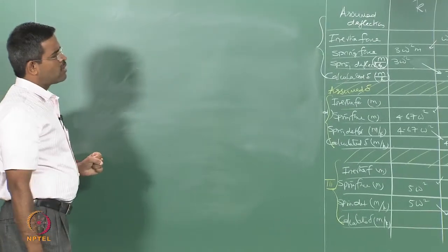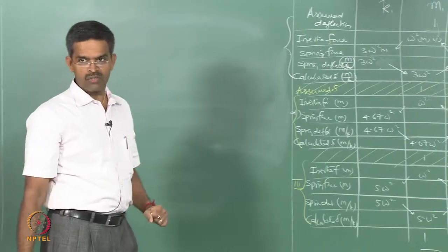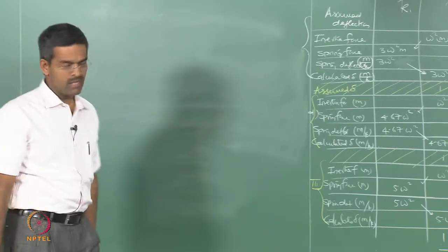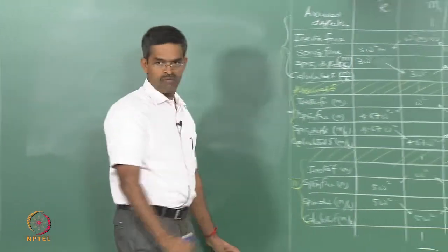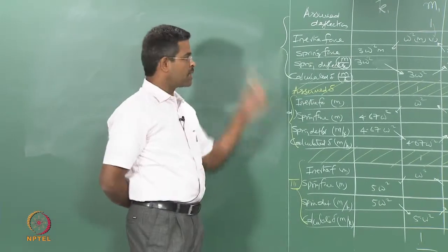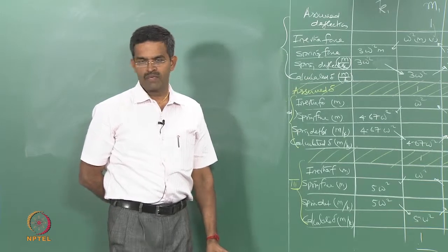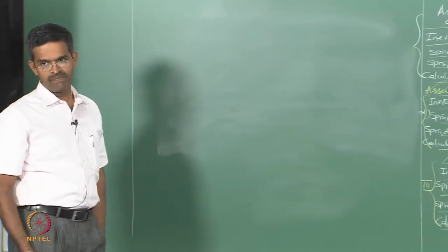So, now I want to calculate the fundamental frequency, but not the mode shape, from Dunkerley. So, I must have the delta matrix with me. Okay. I can directly derive the alpha matrix, which is also useful for the influence coefficient method. From that I can pick up the diagonal elements, and I can also find Dunkerley's frequency from that. So, let us try to derive the influence coefficient directly, that is alpha ij.